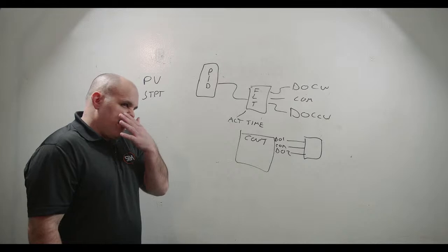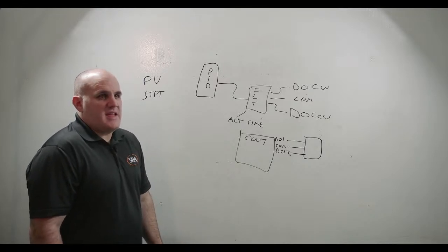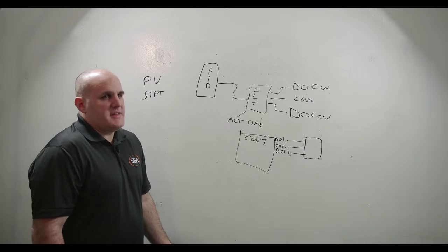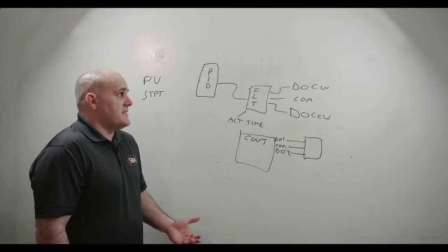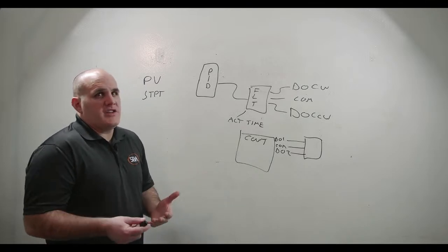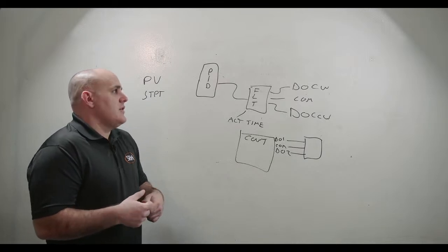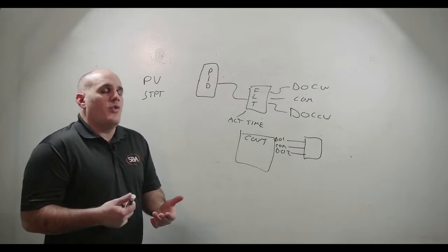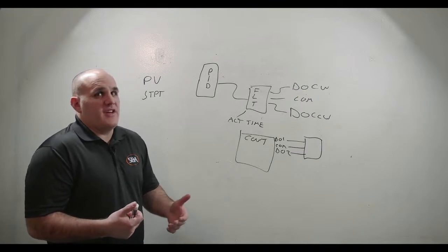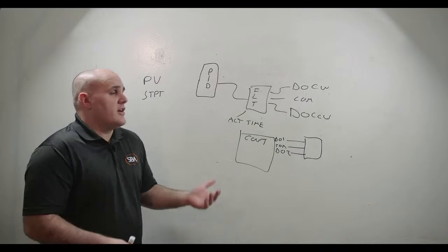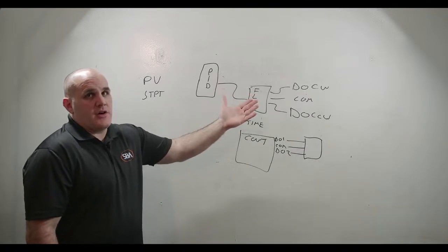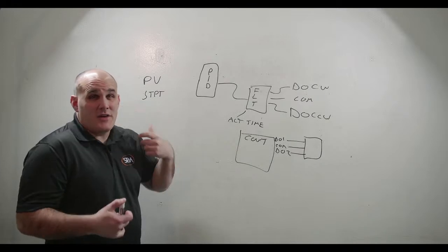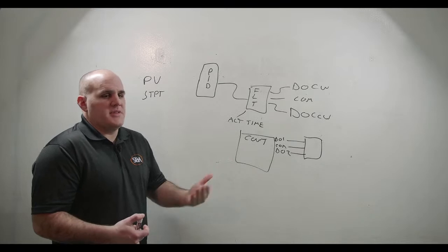And then it says, okay, if the actuator's at 50%, then that means it's stroked for 45 seconds. And if I want to take it to 75%, then I need to stroke it for another 22.5 seconds clockwise. If you don't know that stroke time and you don't have an accurate stroke time, then when you engage that clockwise command for another 22.5 seconds, you may actually overdrive it or underdrive it, because you're turning on that output, either the clockwise or the counterclockwise, for either shorter or longer than it actually needs to be on to drive the actuator to the position it needs to be at.